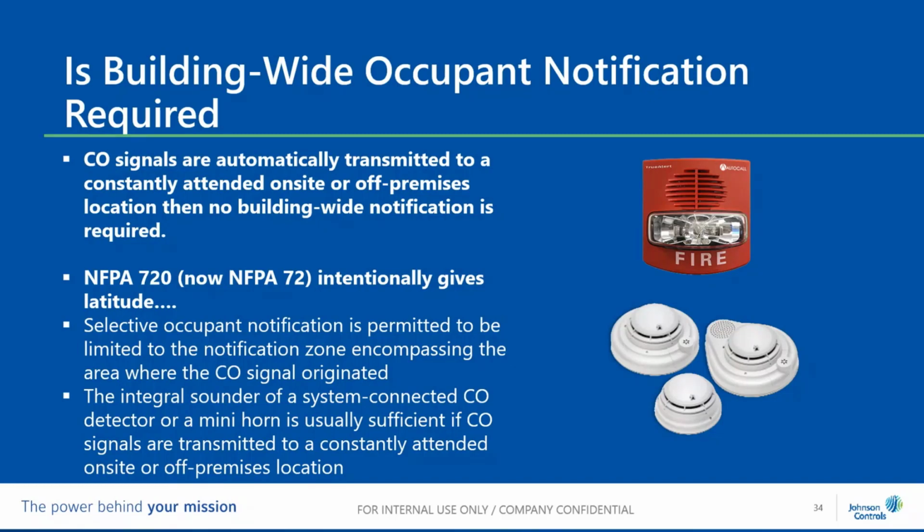Oh, that's a great spot on thing to bring up. So you're exactly right. With Johnson Controls, we now have addressable speakers, horns, and strobes. And just like you said, Dave, we can program them that if I see CO, I can activate that individual device. And we have low frequency also that's now required in these rooms to activate. So it doesn't have to be the sounder base. It could be our addressable AVs that can do that too. Speakers, horns, or strobes. Great point.